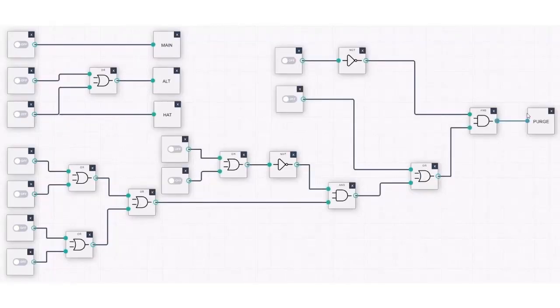Let's take a look at this stairway fan one more time here. What we added was, in the command center at the fire panel, a couple of ASM switches. One of them is a manual run switch to manually start the fan. The other one is a manual off switch to shut off the fan if it's running. This is for fire department use, typically in an emergency.